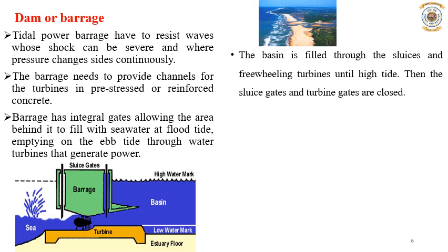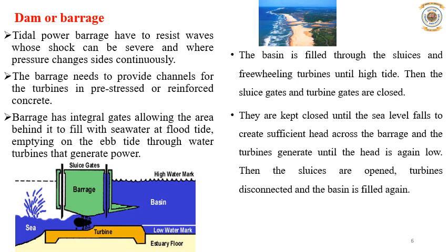The basin is filled through the sluice and freewheeling turbines until high tide. Then the sluice gates and turbine gates are closed, and the flow stops.